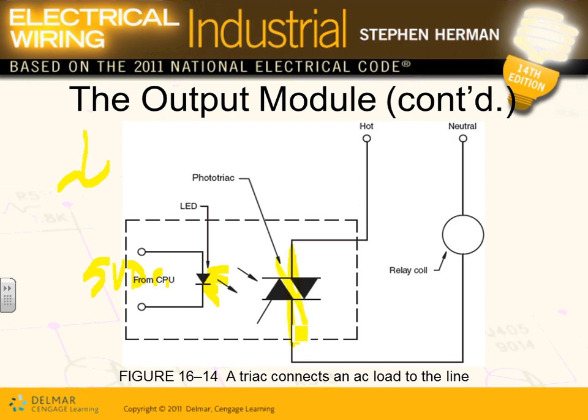It shuts, and I have 120 volt coming in. Now this relay is on. So this triac, guys, acts like a switch, exactly like a transistor. Instead of manually opening it, it senses the light came. When it picks up light, it closes. That's what it means. When it closes, it brings 120 volt into the coil. Now, what can this coil do with that voltage? They put it into a contactor here.